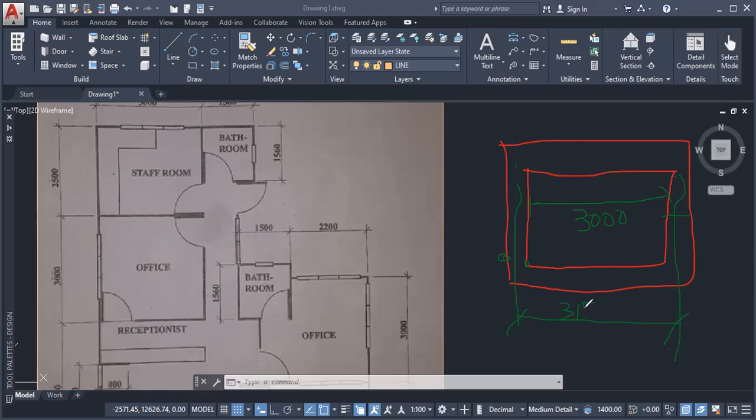3,150. So it is important to establish this from very early, as half of the wall thickness from here is 75, sorry, and from here to there is 75. So when we are using center to center justification and we want inside wall to inside wall measurement, we must add the wall thickness to the dimension that we're given.